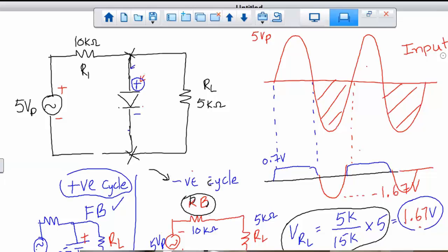So if, let's say, you have 15 volts as the power source and no resistor, where does the excess voltage go? With no resistor, it won't be a clipper. You must have this resistor right here. If you want a clipper, you need that resistor right there. What if you take that away? What would the circuit become?